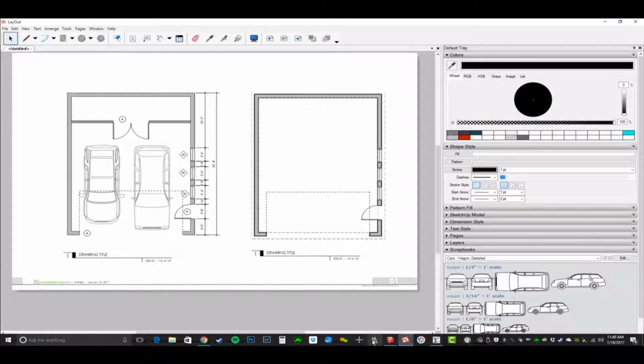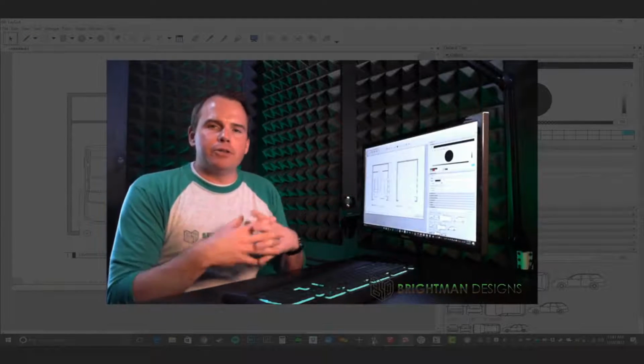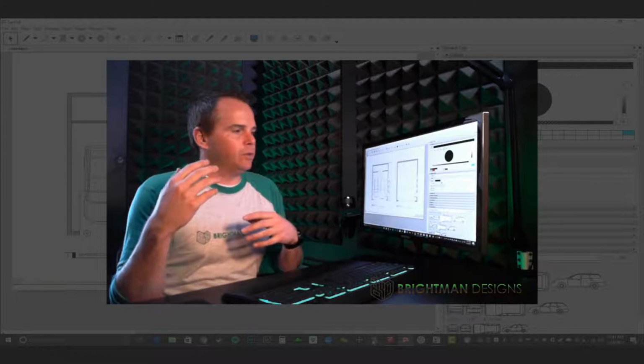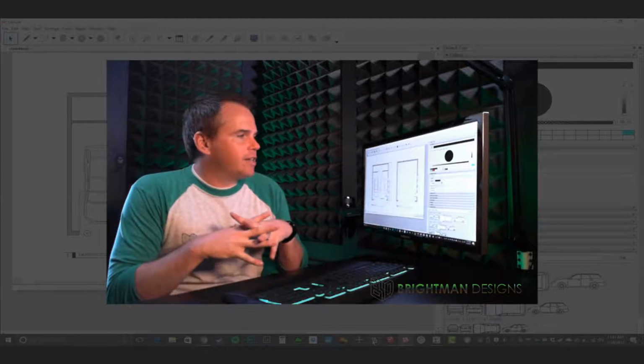All right, so let's talk about exporting to AutoCAD. Something that's critical when you're creating construction documents is the ability to work with consultants. So you have to kick them out DWGs or a 3D model or something so that they can work on your drawings, right? Like if you have a structural engineer, I would want to kick this set out as a DWG, and then they're going to import it into probably AutoCAD and then draw their plans over our CAD backgrounds. Now there's a couple different ways to do that.